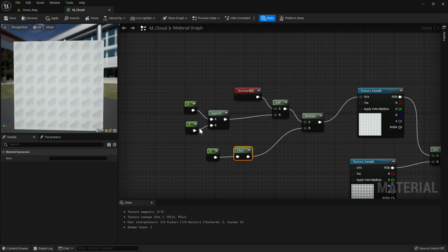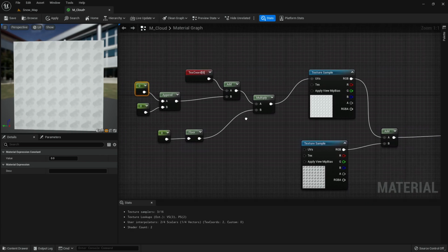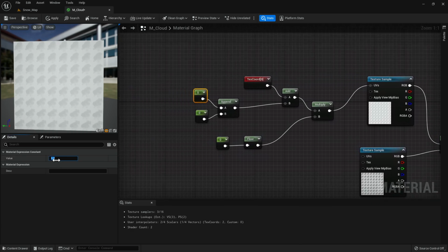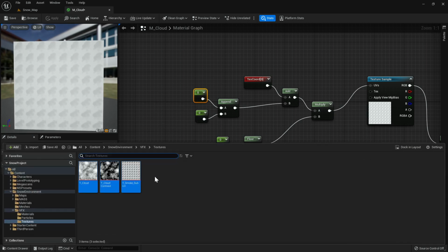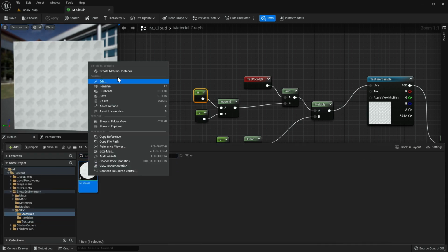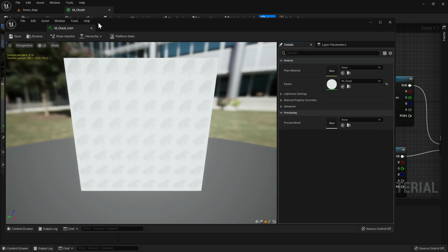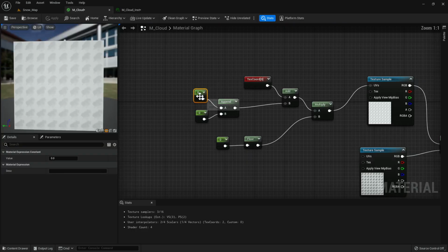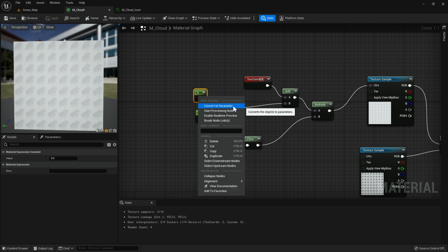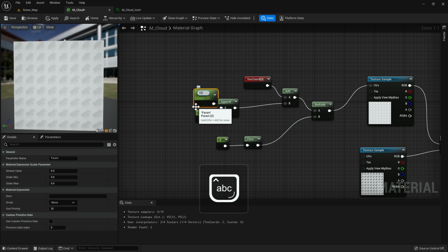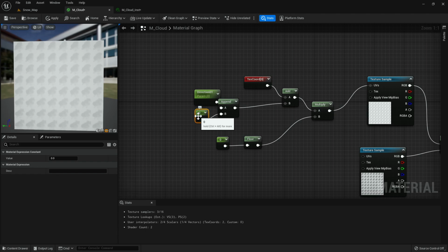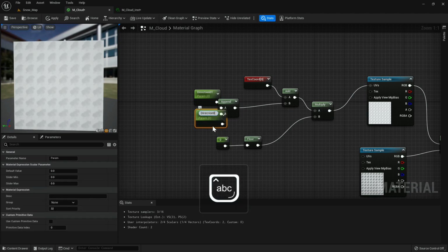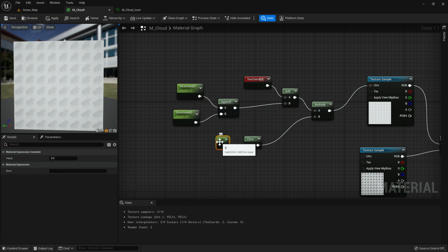All right. If we start moving the constants here, you probably won't see much because whenever you move it, it just loads, right? So we probably just want to make a material instance so it is easier to visualize. So just right click, material instance, and let's enter. If you see nothing, it's because we didn't make a parameter of each one. So let's convert to parameter. Let's say direction 1. Let's name this parameter again. Okay. And this one is gonna be opacity.